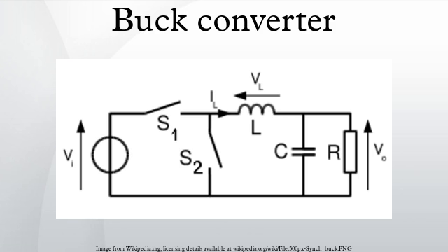These expressions have been plotted in Figure 6. From this, it is obvious that in continuous mode, the output voltage only depends on the duty cycle, whereas it is far more complex in the discontinuous mode. This is important from a control point of view.